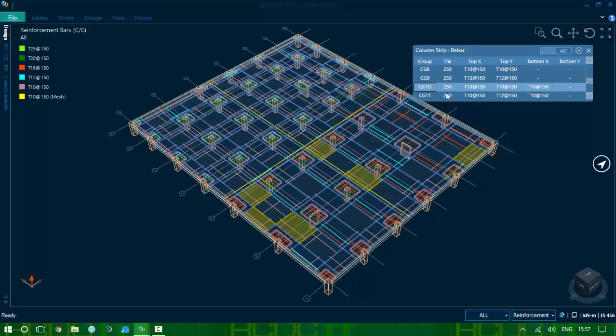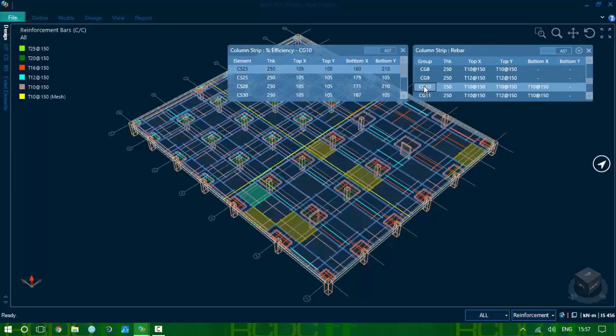And what you can see in this view is the thickness, the reinforcement required and so on. Now, you also have a toggle viewer, if you do not want to see the bar dia combination but want to see the actual area of reinforcement required, you can visualize that also by toggling here. So multiple options to zero in and see whatever you wish to see. What you can also do is come in and click on this window. When I do that, it gives me all the constituents of this group, all the individual elements which constitute that group.